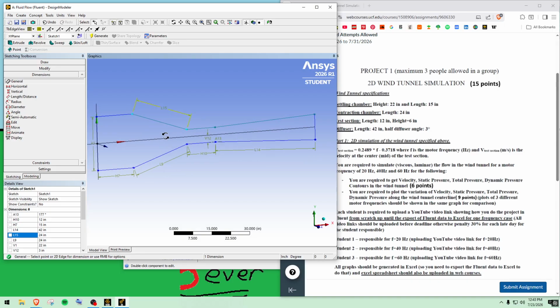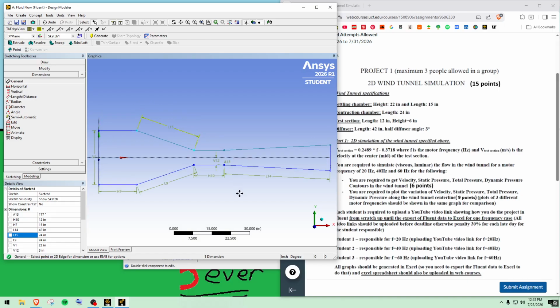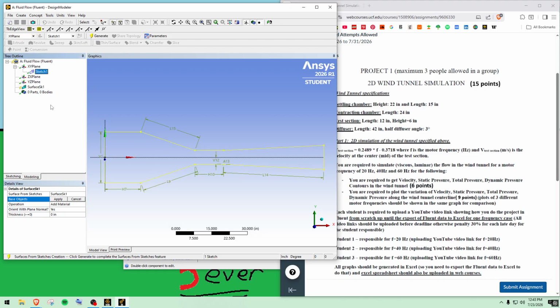Still not really, oops. What's happening? Okay. I mean, we know it works, so I think it should be fine. So back to our modeling. I'm gonna go under concepts and then surface from sketches. And then I'm gonna hit sketch 1, and apply on there, and then generate.